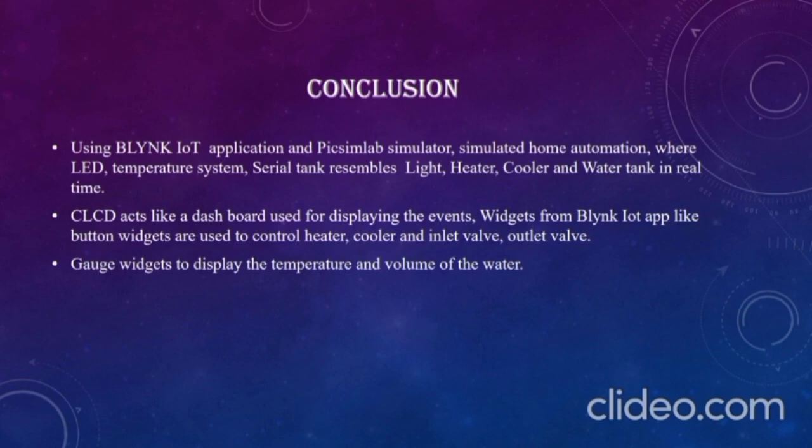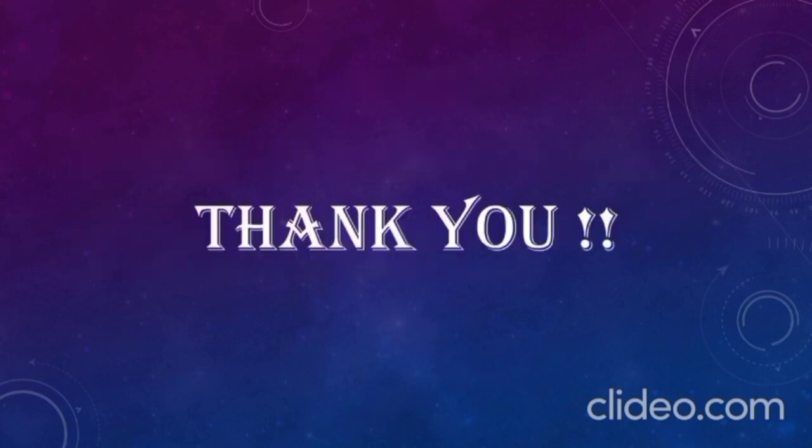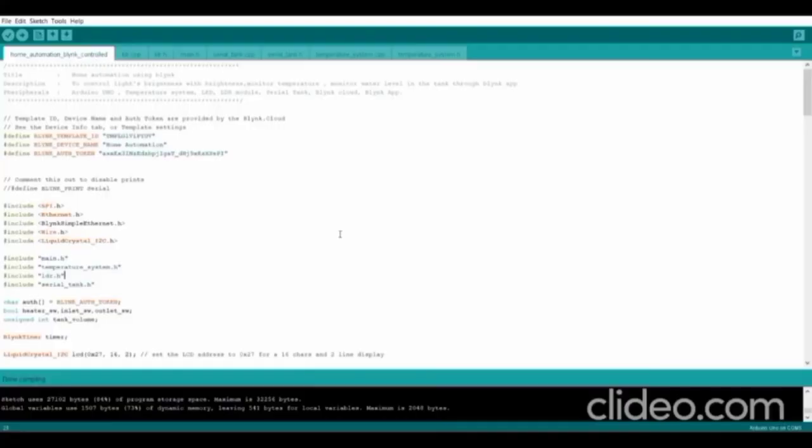Next, PCF8574 is an I2C silicon CMOS circuit. It provides general purpose remote input and output expansion for microcontroller families with a two-line bidirectional bus, and consists of a bidirectional port and an I2C bus interface.